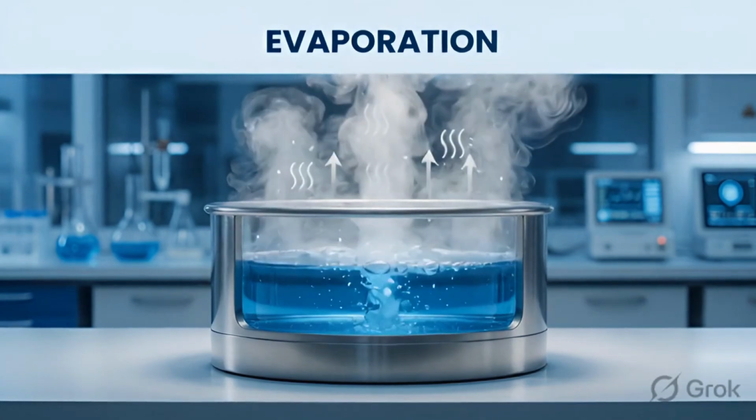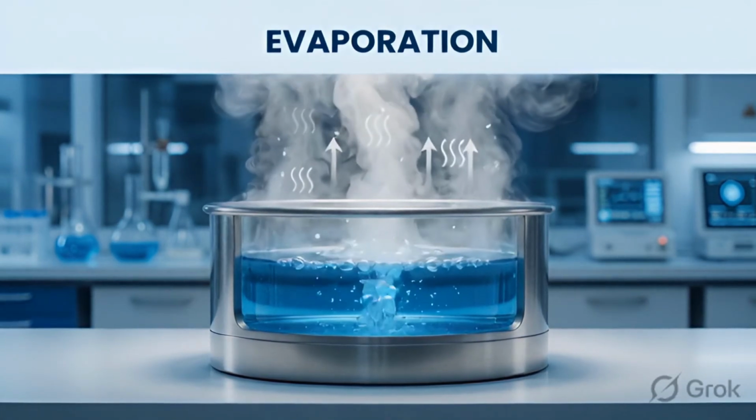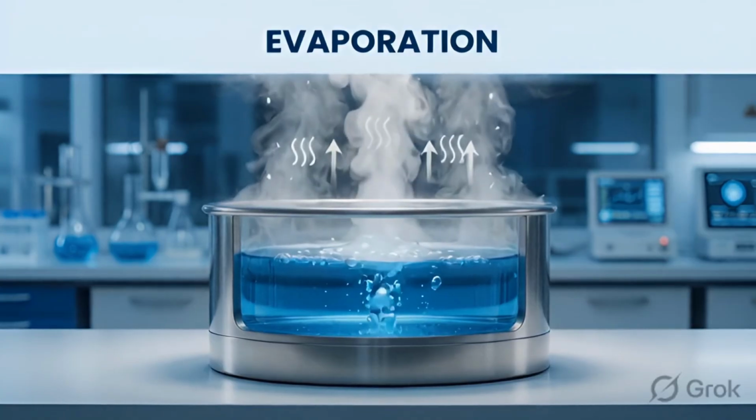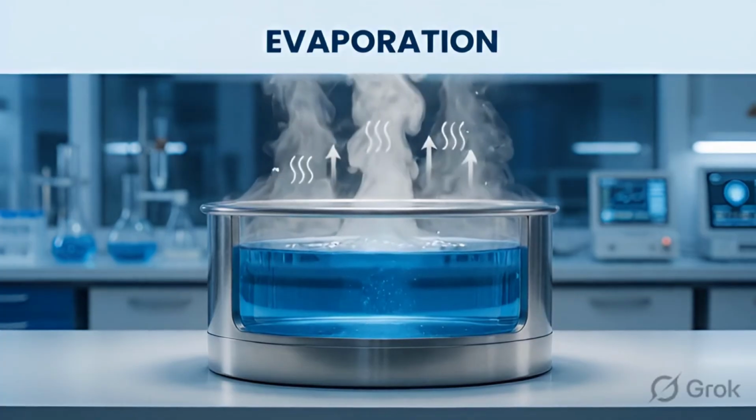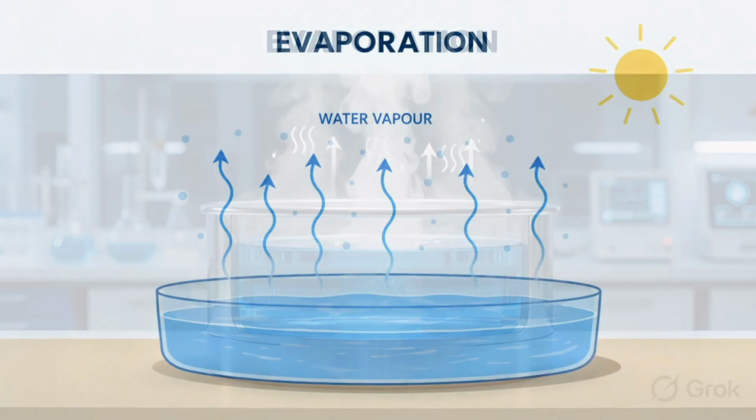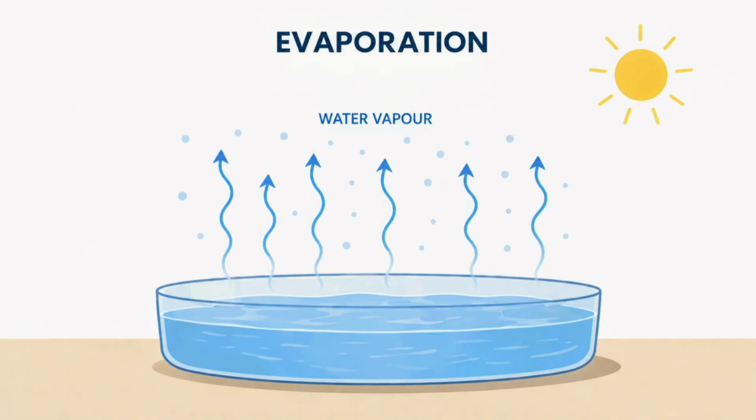During evaporation, the heat increases the kinetic energy of the molecules, allowing solvent molecules to escape into the atmosphere as vapor. Evaporation occurs faster at higher temperatures because more molecules gain enough energy to leave the liquid surface. This process is widely used in the pharmaceutical industries to prepare concentrated extracts from medicinal plants. For example, aloe vera extract or tulsi extract is prepared by evaporating excess water. One important point is that heat sensitive substances require controlled temperature during evaporation, otherwise the drug may decompose.